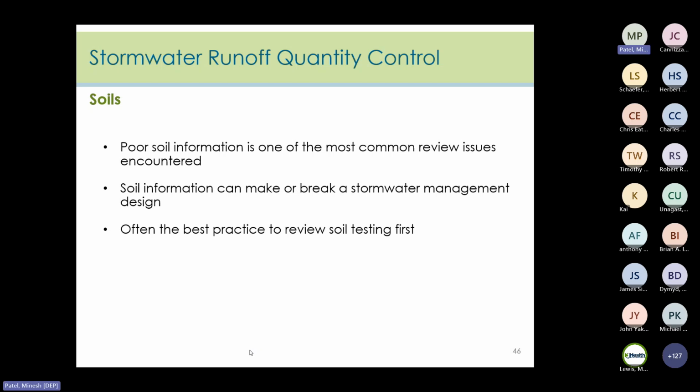Making sure that the soil data for the site is accurate is a critical part of the review process. Inaccurate soil information can make or break a stormwater BMP, so a good practice generally is to review soil testing first.